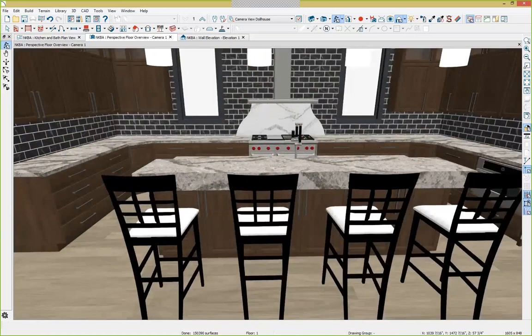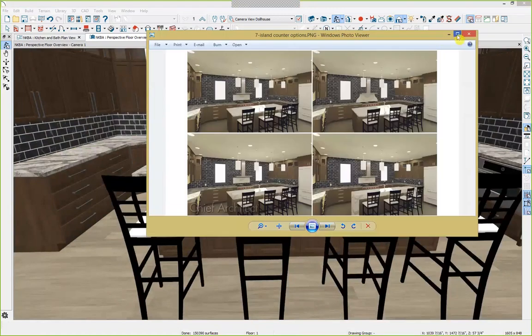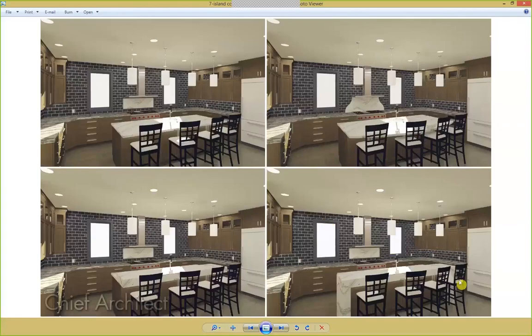So the last option we're going to show is going to be waterfalling it down either side. So our countertop is 6 inches thick. It comes over here and then it goes to the floor. And the countertop on the sides is 6 inches thick. So we need our overhang to be overhanging a total distance of 6 inches.